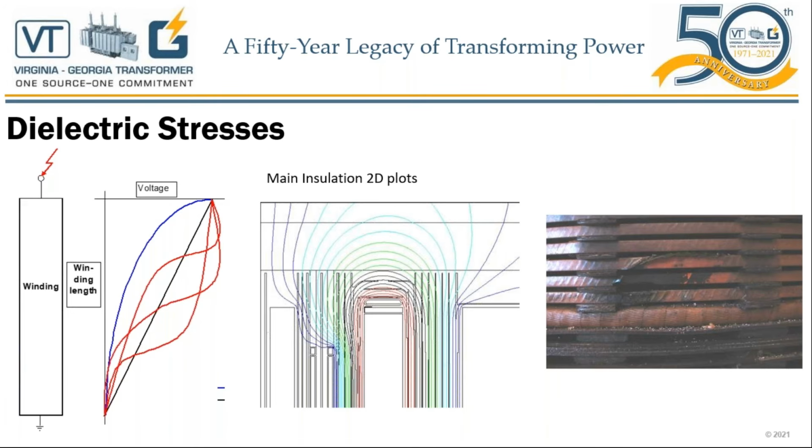If you look at the picture on the right, that is a dielectric field failure. It may or may not cause a catastrophic failure in the field, depending on the protection system. What you can see here is the very bottom, right under the first disc, there is a ring that has paper covering on it. That is a static ring. That is your capacitor that's actually connected to the very first turn of that winding. Then we go to the first disc and the second disc. So in this picture, you are seeing a dielectric arc between the two discs.